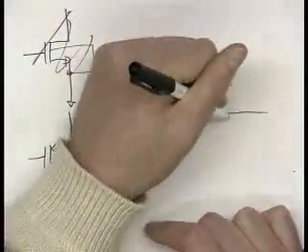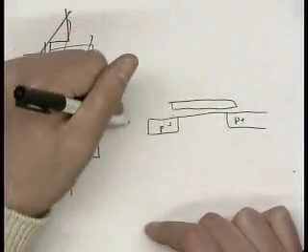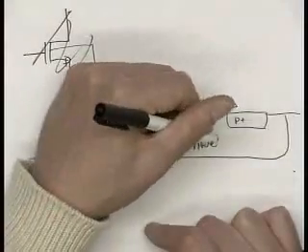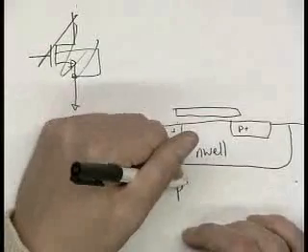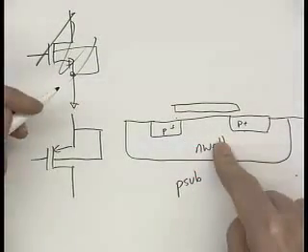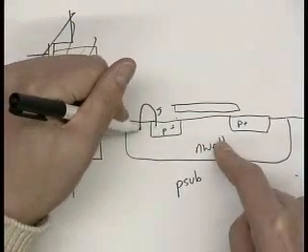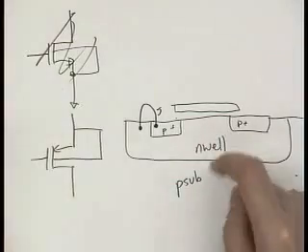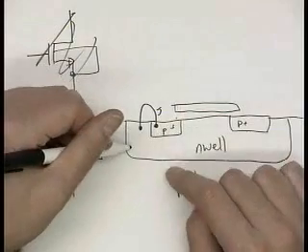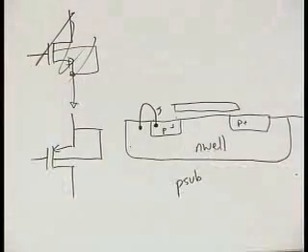plus region, P plus region, you've got an N well here, and then P substrate here. Okay. The reason why is that you can no longer, if you connect, so this is the source, if you do a little connection here to here, you can't connect this bulk, this N well to the N wells of any other devices. So you need to sort of isolate it.